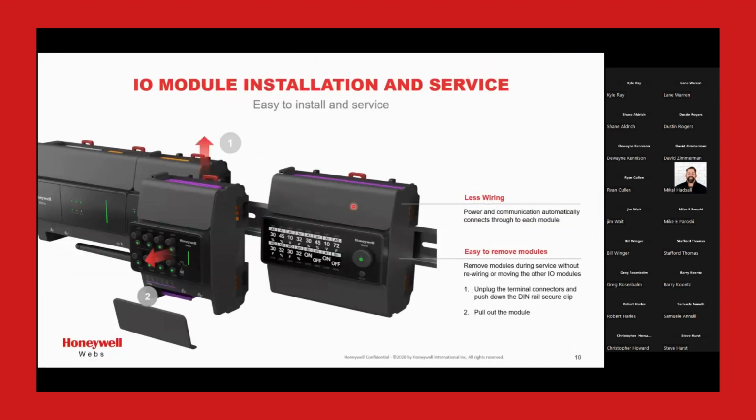They'll slip on the DIN rail, and they will carry with them the RS-485 and the power. And if you have to go away from the DIN rail or remote mount, there'll be a little screw terminal adapter you'll plug in there and you can remote mount the I/O either on the next DIN rail down or 1,000 feet away because it's an RS-485 trunk.